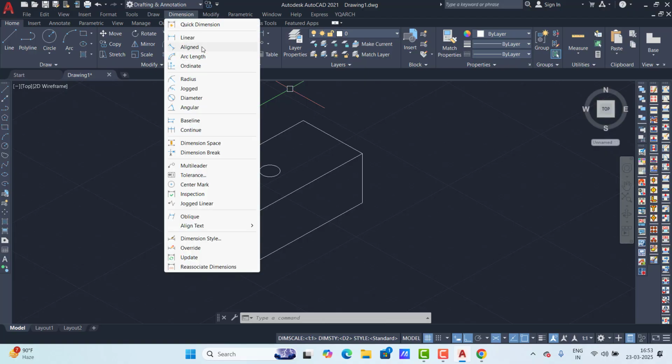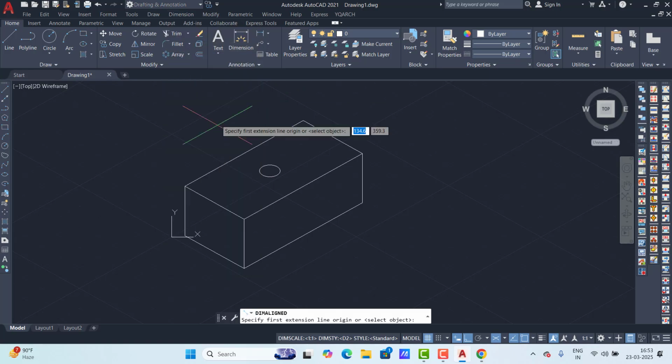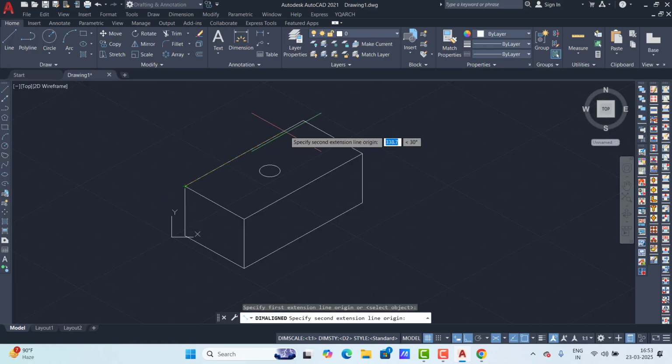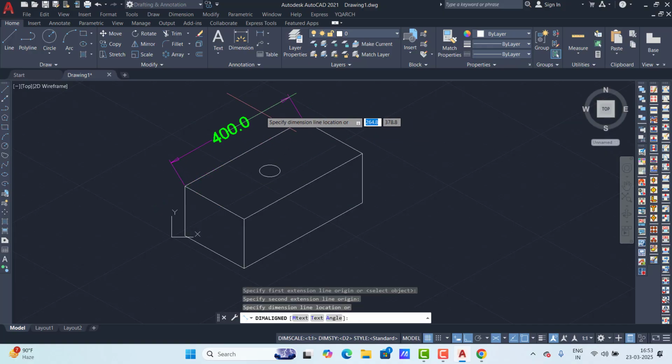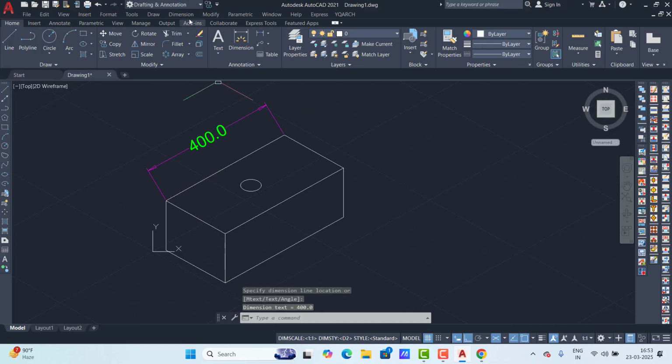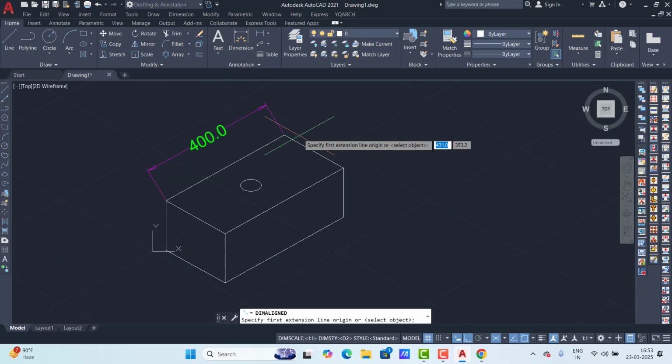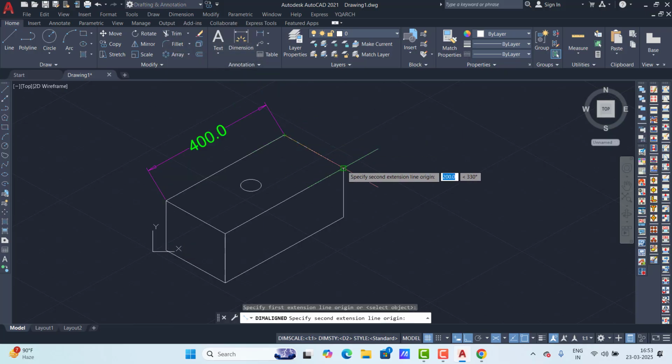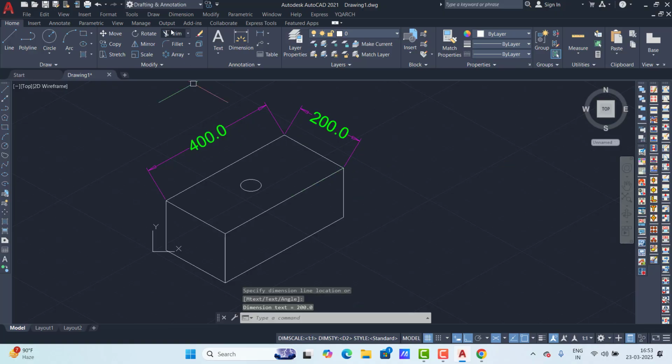When you make this kind of drawing, always just follow the method. Always we have to make a vertical line and a center horizontal line. So for vertical and horizontal we use the construction line. The shortcut is XL. Now type D, enter. XL, now type H, enter. So these two lines I have added. Okay, this one you can manage with a different color. If you type the line type as center line, you can set the center line type this way.